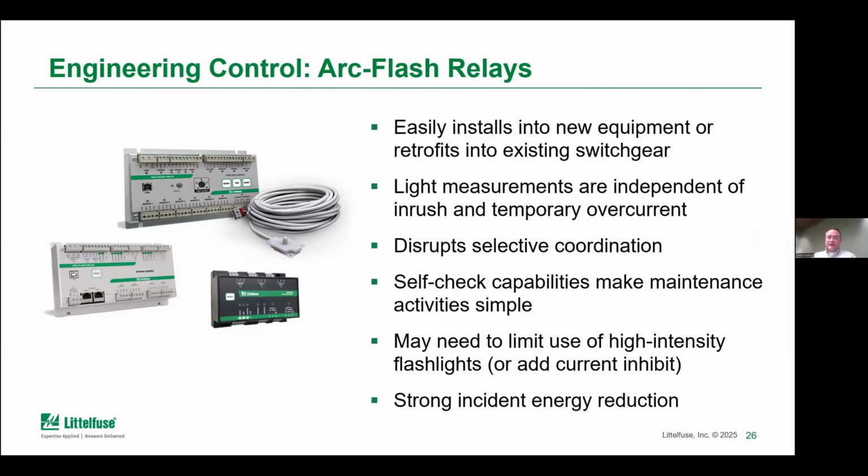One thing that is really good about the arc flash relay, in my opinion, is that it has quite a few self-check capabilities that allows it to be installed quite easily, but makes maintenance activities simple over the lifetime of the equipment, because the relay can self-monitor its ability to detect light.